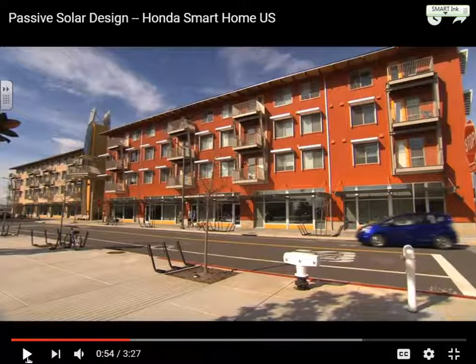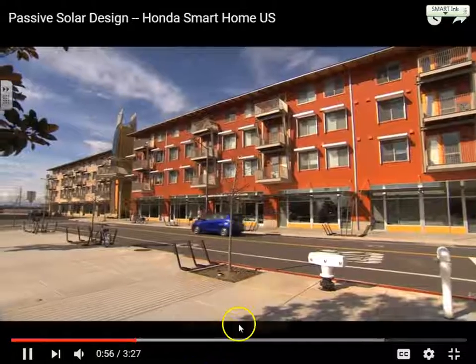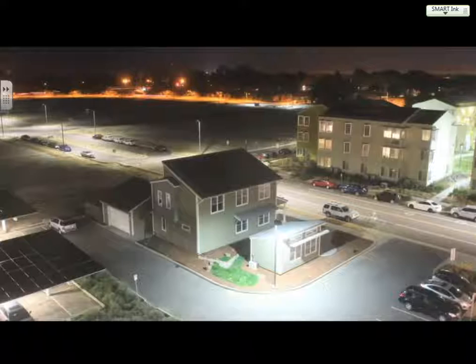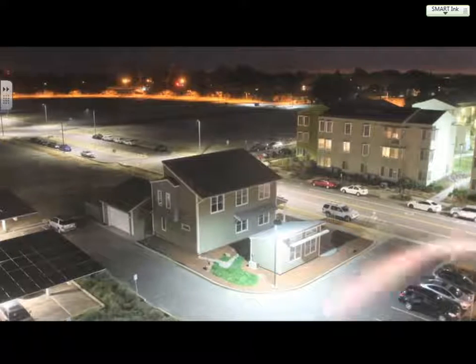So notice he said we're building a building to work with nature, and that's the basic premise of passive design. As much as possible, this lets you really reduce the amount of energy that's needed for heating and cooling. So we're looking at how you work with the local climate conditions, how you position the house on the site for maximum efficiency, and then how you build the outer layers, the shell that we call the envelope.